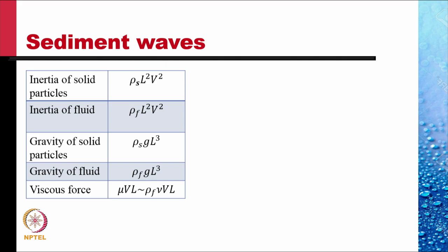Inertia of the fluid, which will be like rho f, the density of the fluid, times L squared V squared. The gravity force, the weight of the solid particles, which will be rho s g times L cubed. And the viscous forces, which would be like mu V L. Mu is of the fluid, so mu is replaced here by rho f, the density of the fluid, times kinematic viscosity.